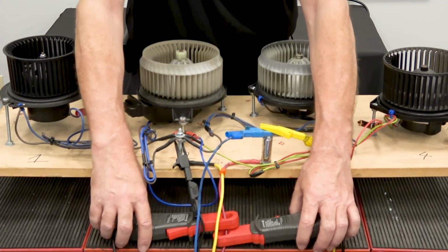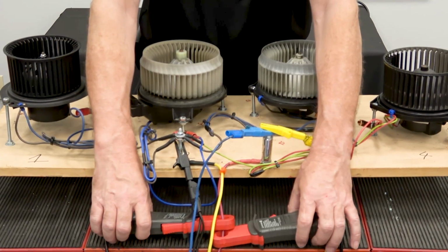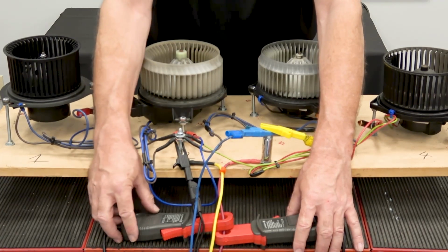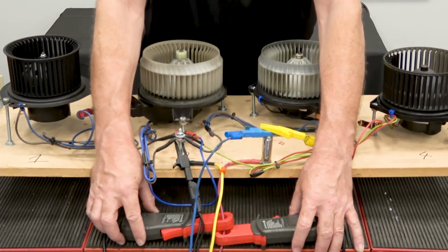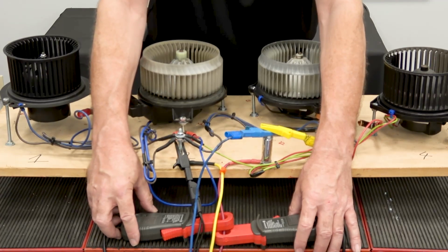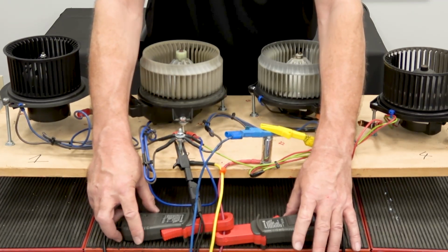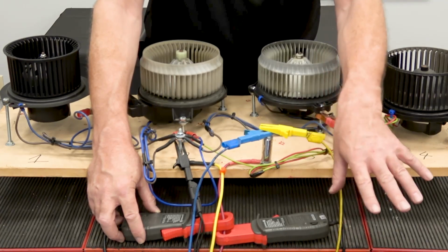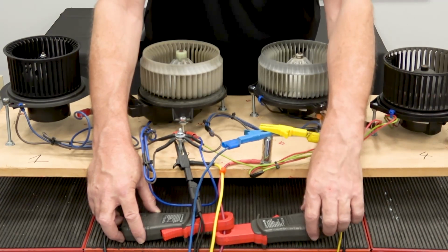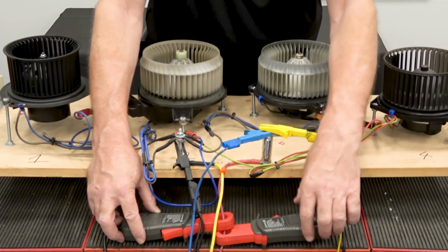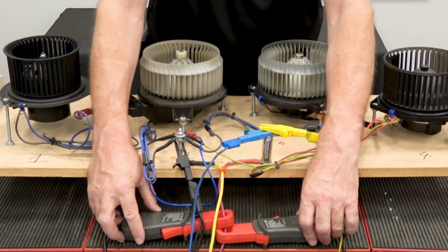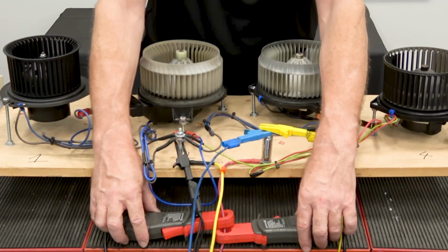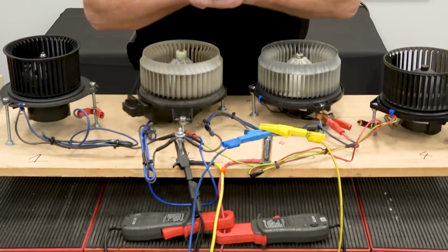Now, you'll note that I've got 2 identical current probes on the same wire, and the reason for that is, in the interest of time. You could do this at your shop, but you can get the same job done with just 1 probe. But in the interest of time here, I'm going to look at one of these current probes in AC coupled mode, and we'll look at the other probe in DC coupled mode, and we'll be able to look at 2 different characteristics of each wave pattern with these 2 current probes.